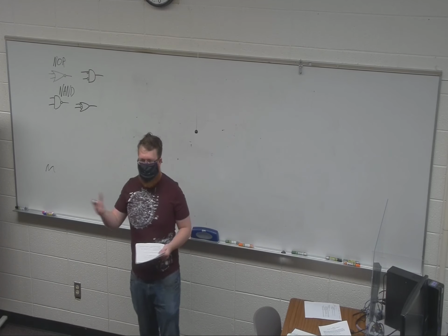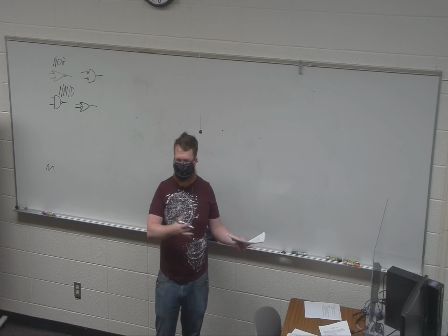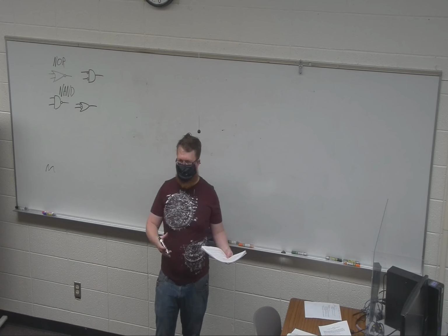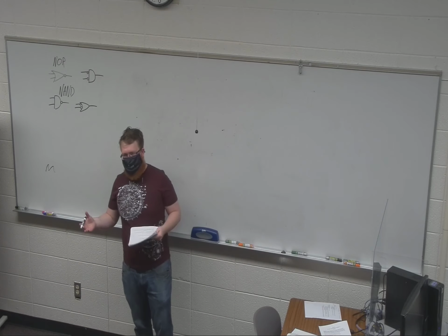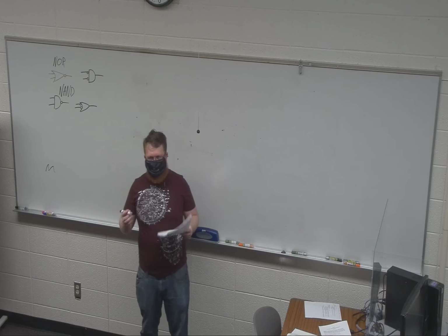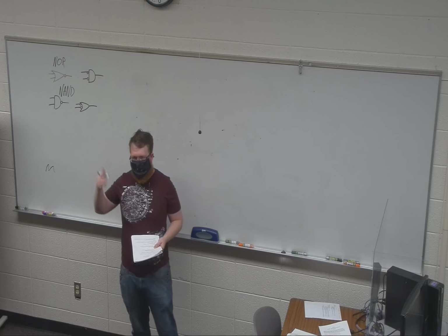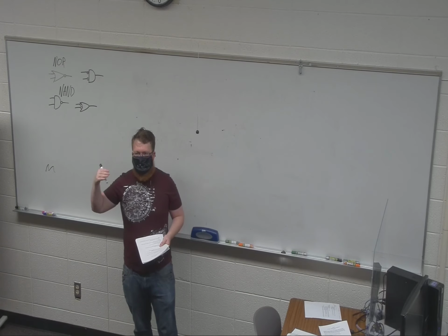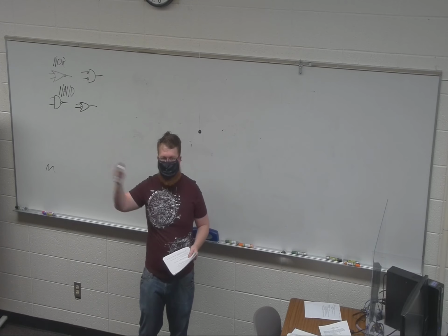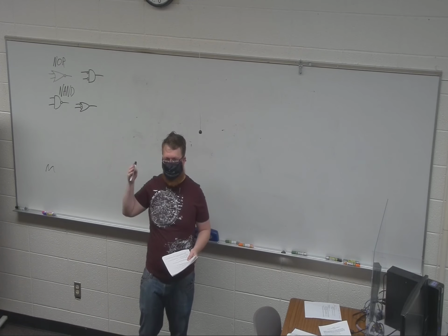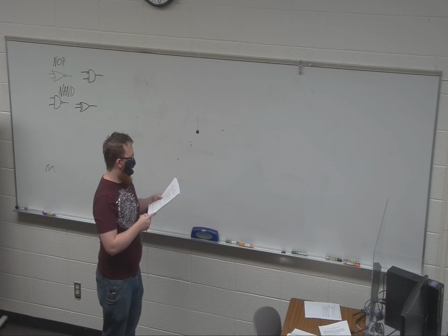Now, when you step into flip-flops, we start going from combinational logic, which is the focus of all these things, to sequential logic, which in a simple way of thinking about it usually means that it's clocked, right? Things are going to happen one after the other, whereas with the gates we use, they change as fast as they can. With flip-flops, they don't change until you clock it. They don't care what's happening in between the clocks.